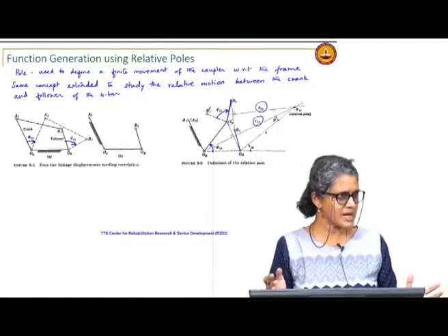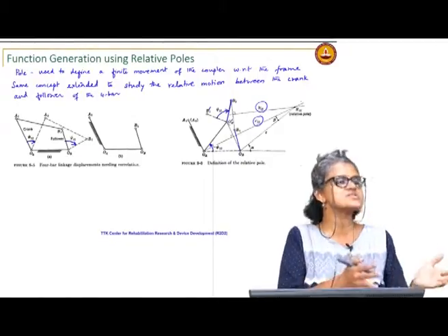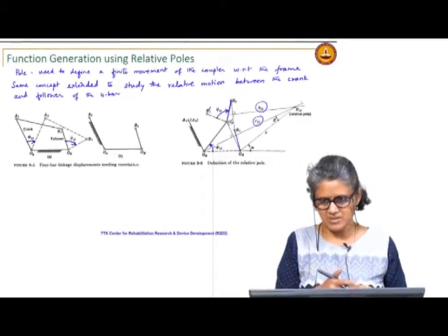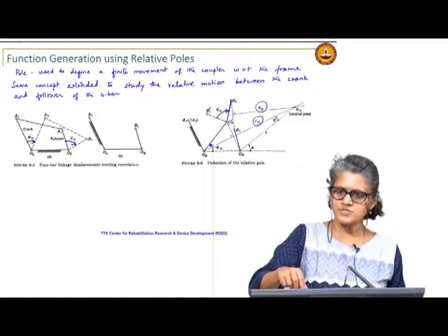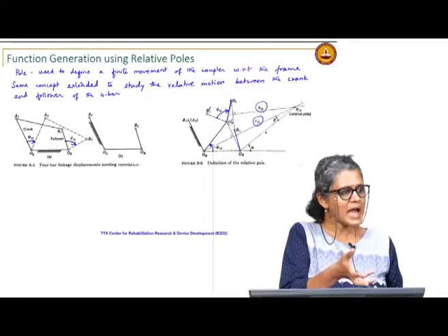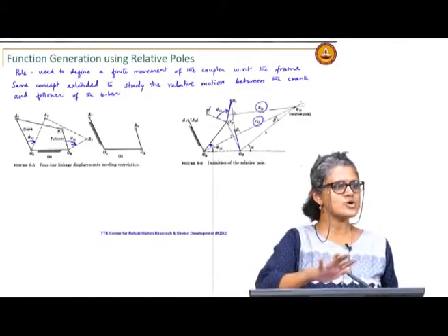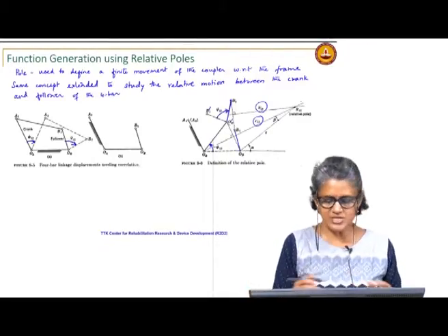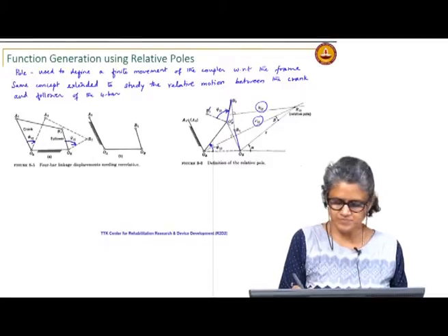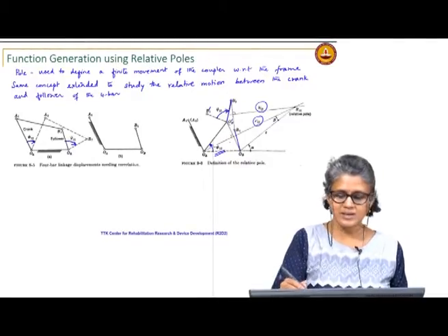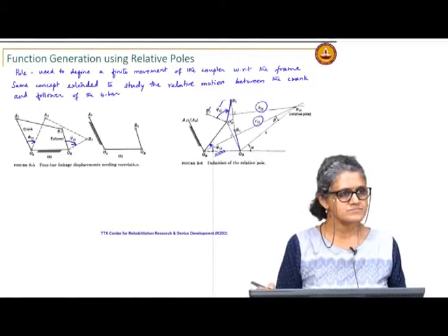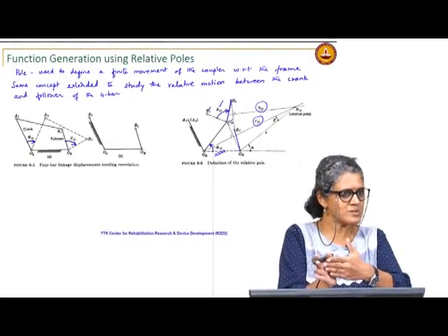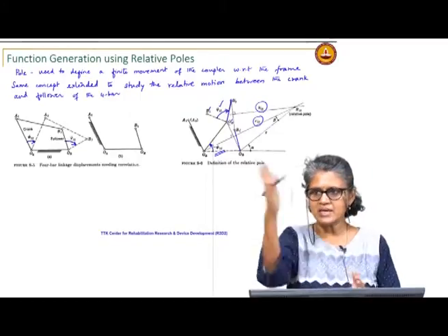The only reason we call it the relative pole is that in my original linkage it is not the fixed link. So, it is the same concept. OB B1 moves to OB dash B2 dash. So, these two rotations can be combined to a single rotation about this relative pole. Which are the two rotations? Minus phi 1 2, this one, and psi 1 2, this one. So, if I look at OB B1, first it is moved by minus phi 1 2 and then by psi 1 2.